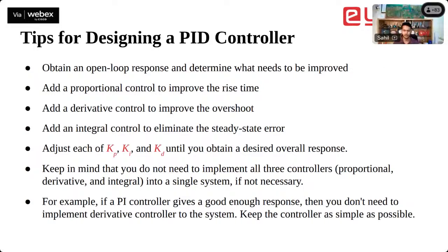So now, the basic tips for designing a PID controller. When designing a PID controller, we have to keep certain things in mind. We start with KP: increase the KP until you get a fast response, but you have to watch for the overshoot. When you finally see an overshoot, that is when you have to stop increasing the KP. Then what to do next after we see overshoot? When you see overshoot, you can slowly add Ki.